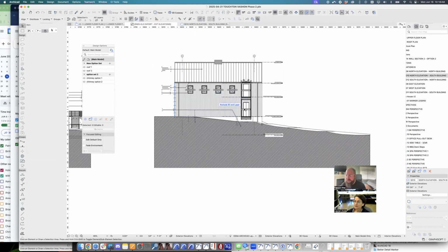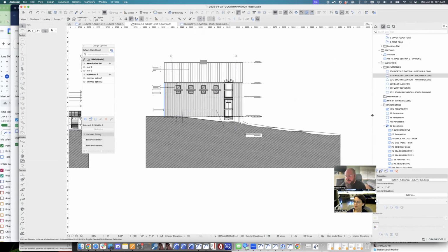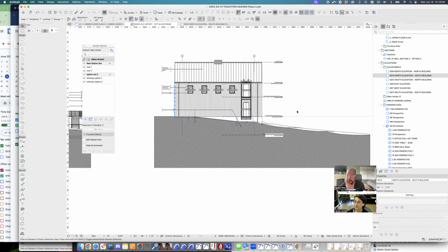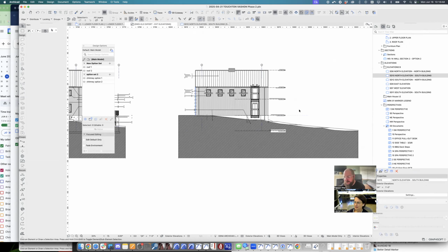Oh wow, okay, that's good to know, because at the new place I'm going to, I need to start setting up the software and figure out a recommendation going forward. I want to keep using this, obviously, but they've had consultants that use Revit. So I'm wondering if we do that, can these models talk to each other, or is that difficult? Revit to ArchiCAD is not that bad. It's IFC export and import basically. There are certainly some tricks to IFC coordination, but it's doable.